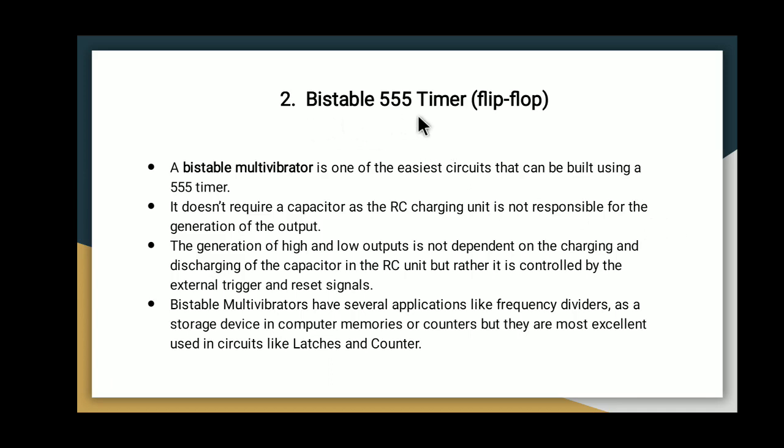Bistable 555 timer. A bistable multivibrator is one of the easiest circuits that can be built using a 555 timer. It does not require a capacitor as an RC charging unit because the output of the bistable 555 timer is controlled by external trigger and reset signals.